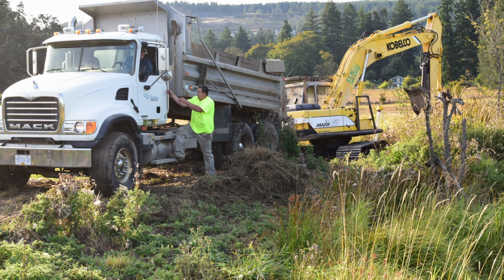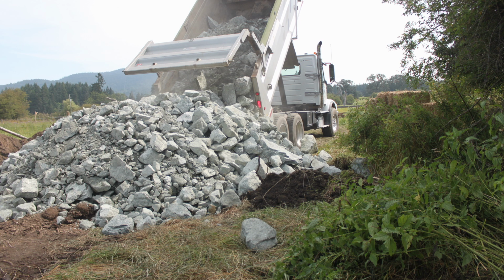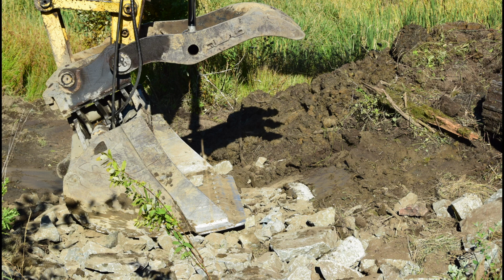The rock needed to build each vertical grade control structure was delivered by dump truck. The dump truck was able to unload the rock close to the structure being built where the ground was dry and firm. In some cases, the dump trucks unloaded the rock further away from the vertical grade control structure being built, and this is because the ground was soft and there was a danger of getting stuck. We then had to use the excavator to move the rock 1 bucket at a time. We used angular rock of mixed diameters ranging from 15 to 40 centimeters to build the structures. We requested that the rock contain fines and smaller rocks so it could be compacted.